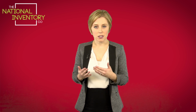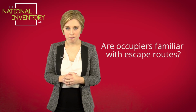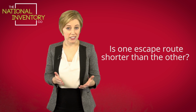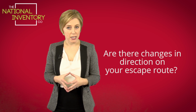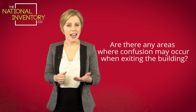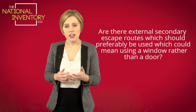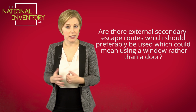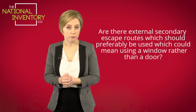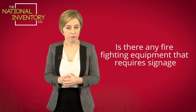To decide if signs are required, you need to consider the following questions. Are occupiers familiar with escape routes? Is one escape route shorter than the other? Or are there changes in direction on your escape route? Or are there any areas where confusion may occur when exiting the building? Are there external secondary escape routes which should be preferable, which could mean using a window rather than a door? Is there any firefighting equipment that requires signage?